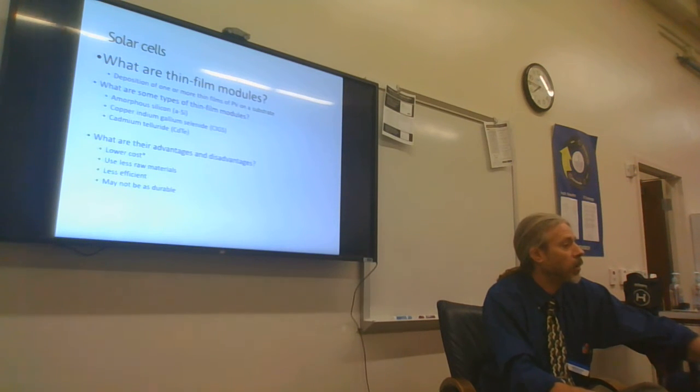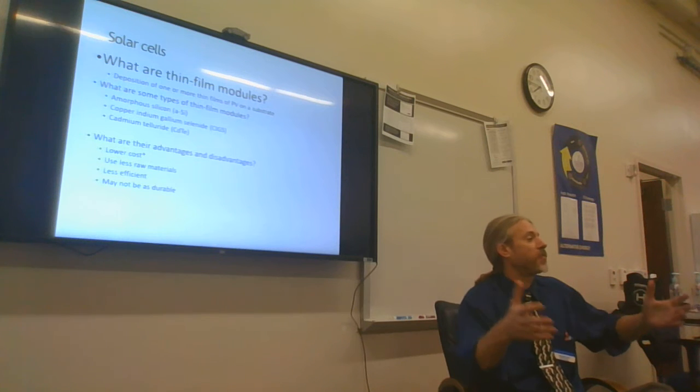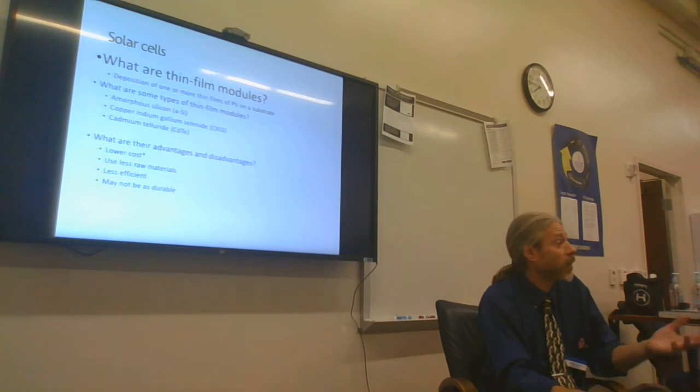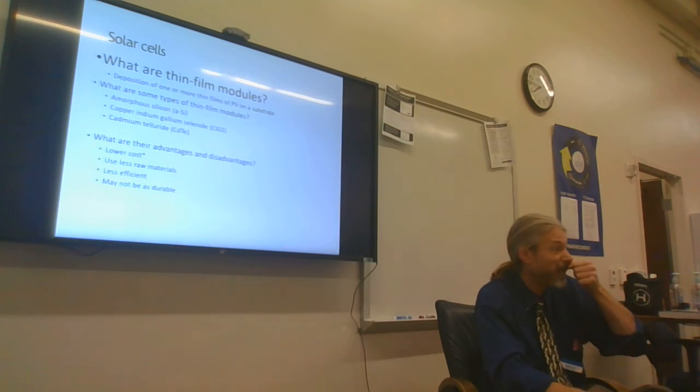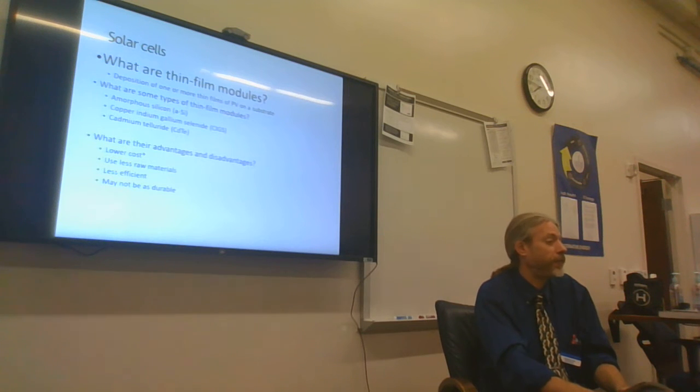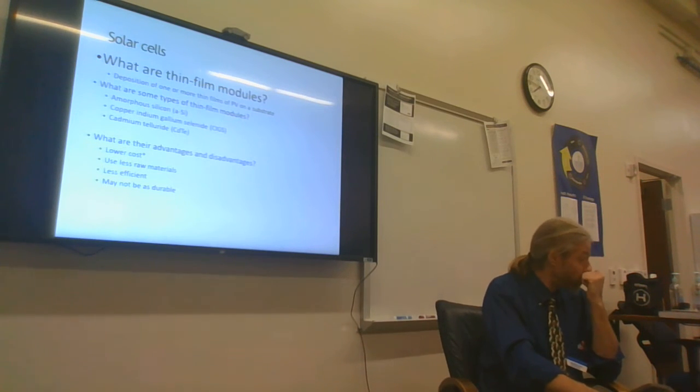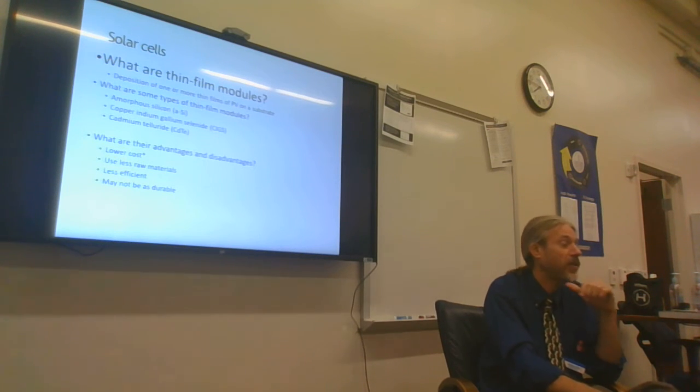So you should not ever have a problem with having higher amperage produced by each individual cell. You might have to have bigger conductors theoretically, right after it's made all of its series connections and it's going into the leads that come out of the wire. Right now, about 15 amps is about the highest amperage that any of them output. And I would say that if you got much more above 22 amps, then you'd have to have larger than 10 gauge wires, just for safety factor.